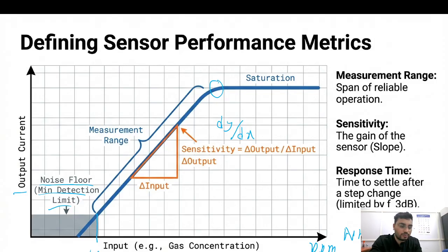The output current won't have that much sensing capability to detect below a few ppm values. So the detection or sensing application of the gas will have a certain range. It can be from 10 ppm to 100 ppm, something like that. If you increase to 1000, it will not work. If you decrease below 10 also, it will have some problem detecting accurately.